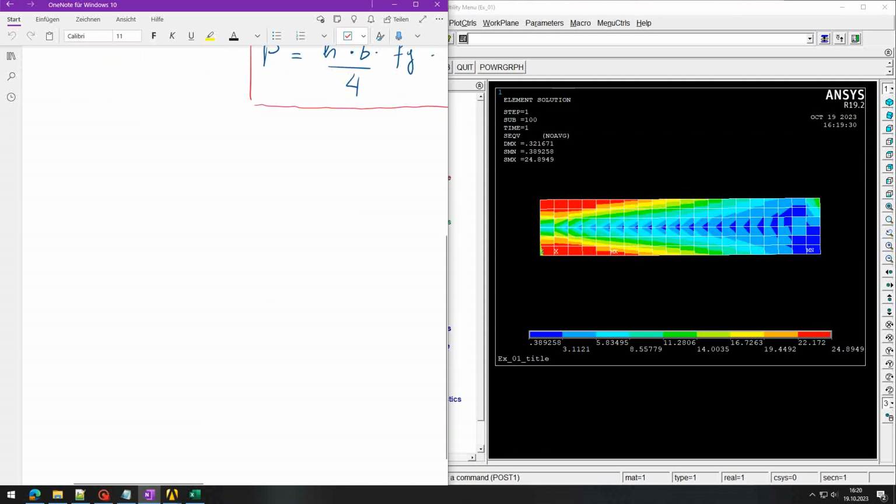We have to wait a little bit until that appears there. Well, in each finite element you have your extreme nodes, but the analysis is not done in the extreme nodes. It's normally done in the Gaussian points, the green ones that you have here.